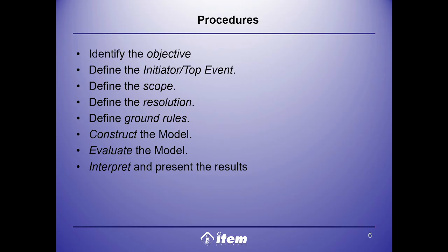We analyze the completed logic to calculate the overall system unavailability, identify the critical cut sets, and calculate the importance measures for individual events. The final step is to interpret the results. We use the analysis to help the management team decide exactly where to invest engineering resources for the biggest safety improvements. This procedure is the backbone of any risk assessment analysis.